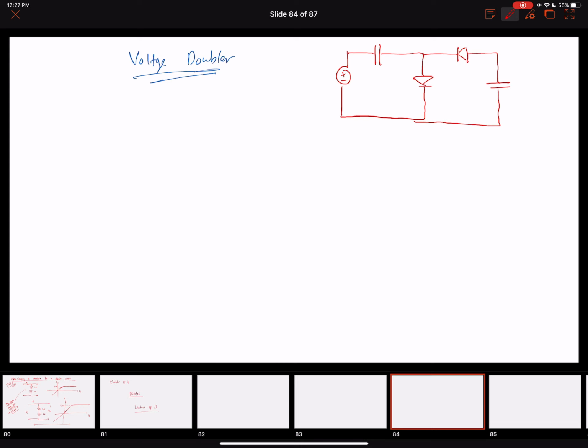another circuit. Now if I look at the second part of the circuit with the diode and a capacitor, this looks more like a peak rectifier circuit. Okay, so this is my input waveform. We have a capacitor C1, plus minus Vp, plus minus Vd1, D2, let's call this D1, C2, and V0. Okay, so we will see how this is going to double the voltage.